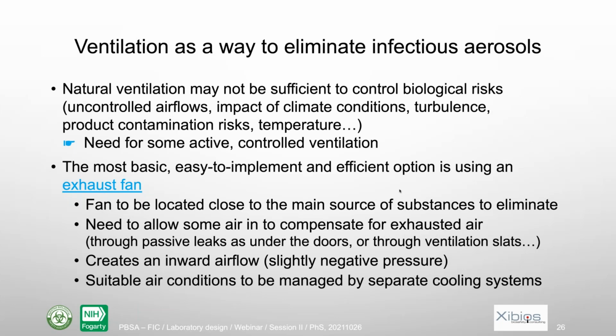And when we decide to use an exhaust fan, there are some rules that we should use. First, the fan has to be located close to the main source of the substance to eliminate. So if we have a good risk zonation with a high risk area at the end of the lab, that's clearly the place where the exhaust fan should be located.